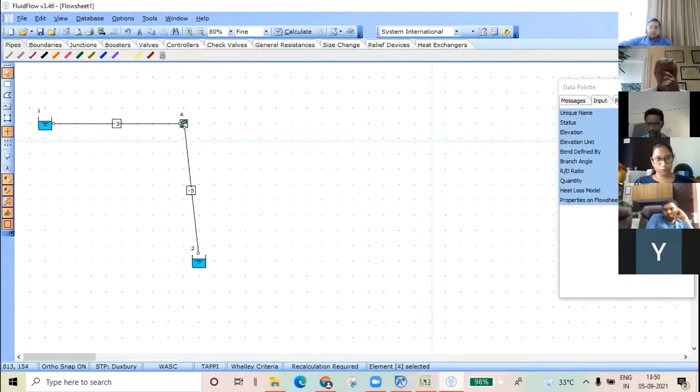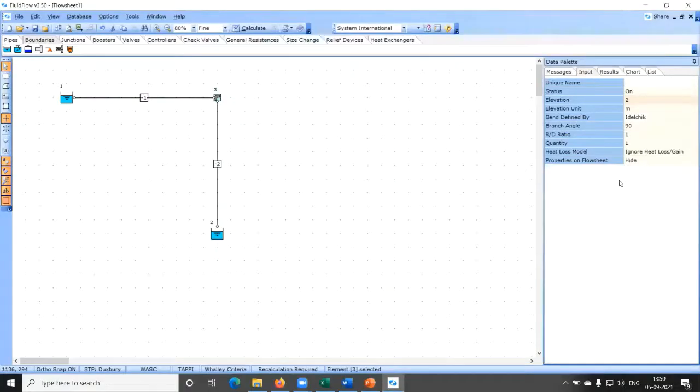I am sharing my screen now. All right, so we are at the bend. The elevation is already provided. Now if there is a bend, you need to have the pressure drop calculation formula, right? So we have got 4 options: either Idelchik, Miller, Crane, or SAE. If I select Idelchik, then it will use one of the formulas given by Idelchik. Idelchik is also a scientist, Miller also a scientist, Crane also a scientist, and SAE is basically 3 scientists put together, right? So let us go ahead with Idelchik.